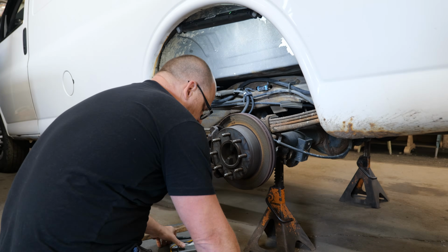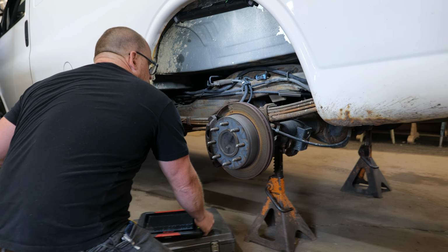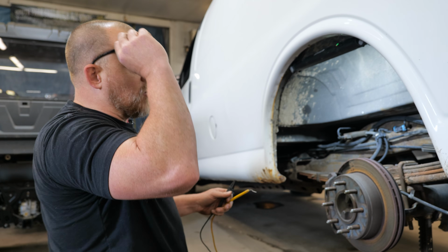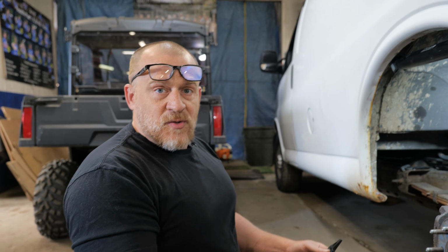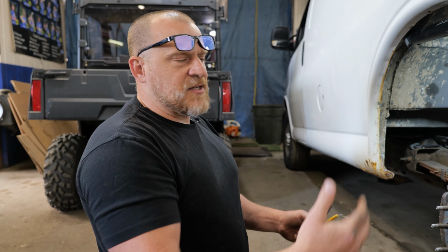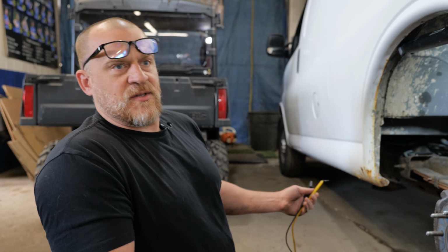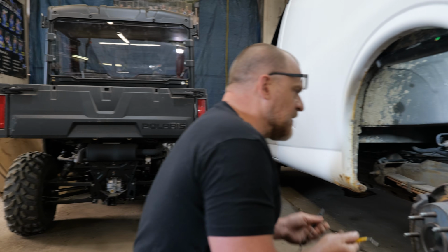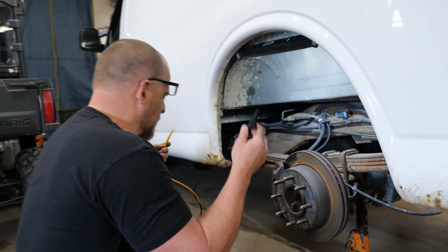All right, so first thing is service info is wrong on this. This is an old school VRS design. Even though my 09 Silverado used a digital signal, an active ABS sensor, this van, even though it's 3 years newer, is the older design. So got to be careful with service info for sure.